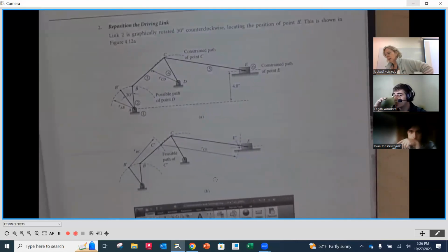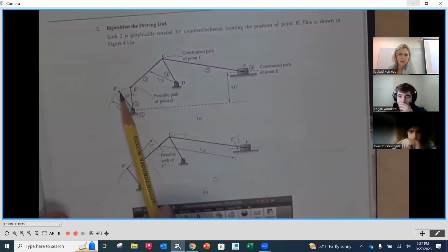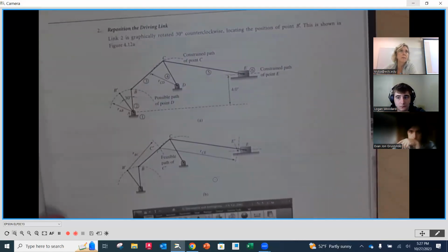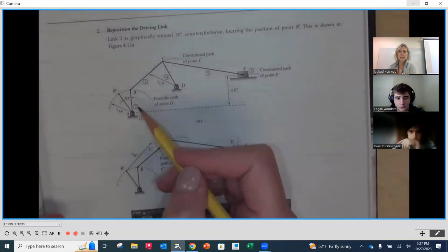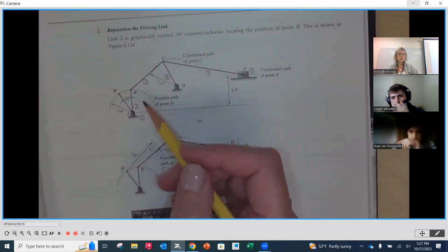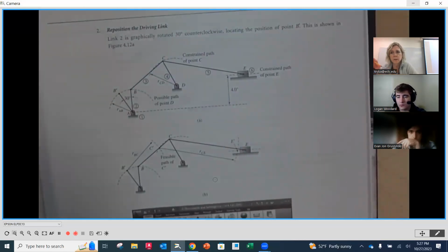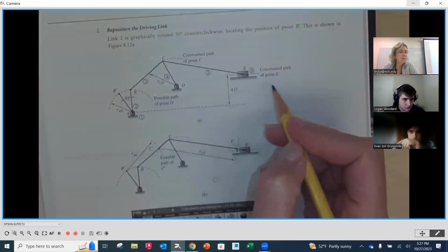So as we're looking here, we're going to now rotate that link number 2 counterclockwise, that 30 degrees. So you're thinking, I can just simply rotate that in AutoCAD, right? You just rotate that link, do a rotate copy so that you leave that other one behind. And then what I need to do is see how the rest of the links are going to move relative to it. So before I even worry about where the next one is going to end, I really need to determine what is the path of anything that's going to move.